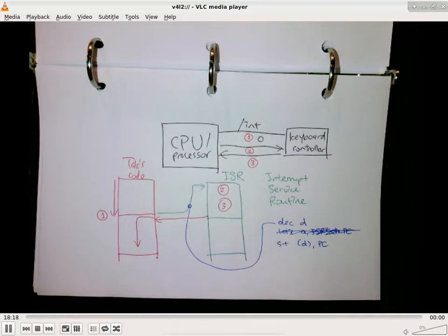That is your stuff. But any location below what the stack pointer is pointing to is, quote unquote, available. And the ISR makes that assumption. It goes like, okay, I'm not going to mess up anything above where the return address is pointing to, but whatever is below is free, is available. Gotcha. Is that okay?